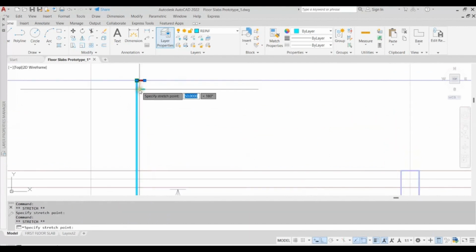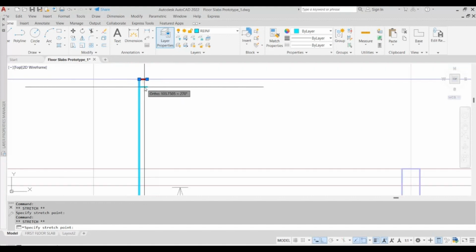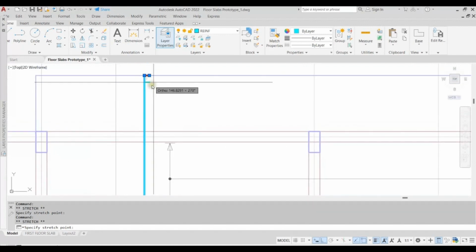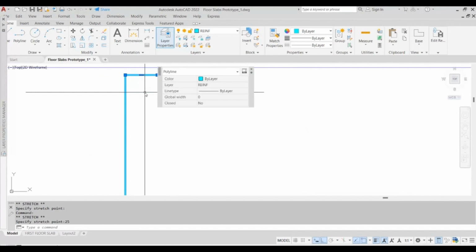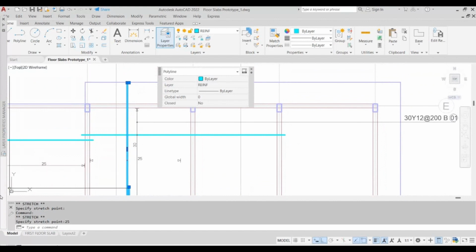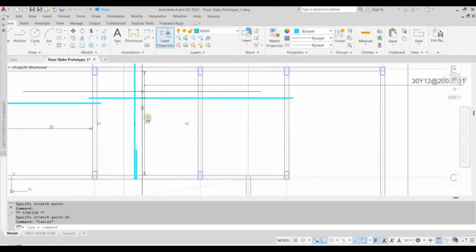Because it's bottom reinforcement, and for a cantilever slab, bottom reinforcement is more or less a nominal reinforcement. So whatever I have here, for sake of ease of placement, I'm still going to extend this, so I don't need to start with a new bar since it's still within. Anyway, we can check the total length, and check it by checking here, which is less than 12 meters.